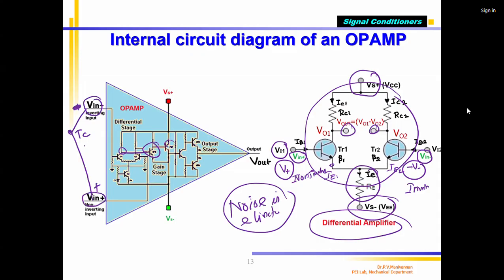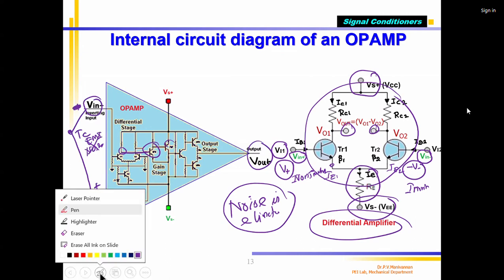So if the thermocouple picks up noise also, EMI noise, correct? The sensor can pick up EMI noise, and that will be automatically cancelled in the output. That is the advantage of the differential amplifier. So that is the plus point of the op-amp. Any doubts?